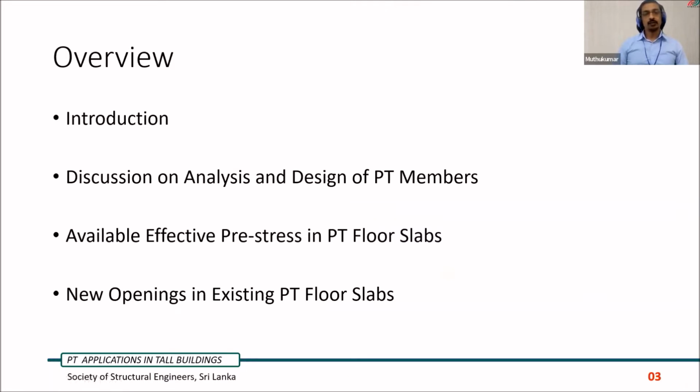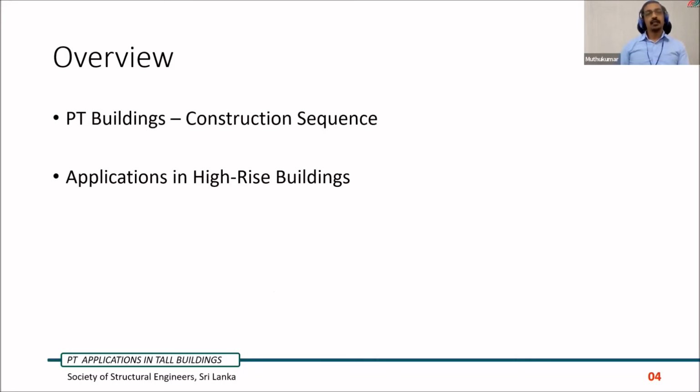We will go through the basic design assumptions and analysis, and what is the actual available effective pre-stress which is considered in design and what could be available practically at site, and the introduction of new openings in existing PT floors. And we will go through the construction sequence which is normally adopted in PT buildings, and general and special applications of PT in high-rise buildings.